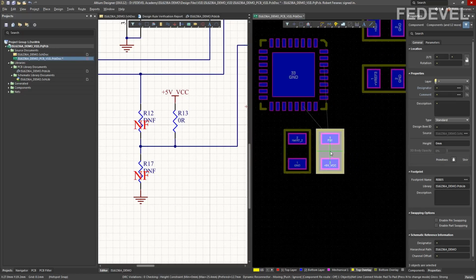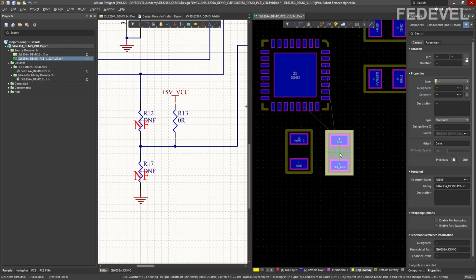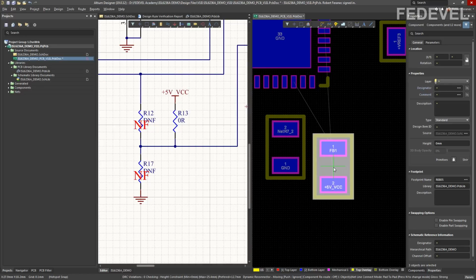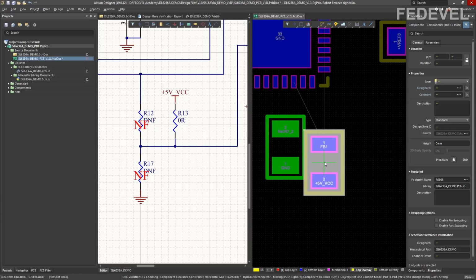Press spacebar to rotate, and I'm going to tell you the exact position of this resistor. So place it into this specific location, which I'm going to tell you, because then it may be a little bit easier for you to do the layout a little bit later. So place this resistor, watch down here, okay? Place it exactly into 27.4 by 18.6, like this, okay?